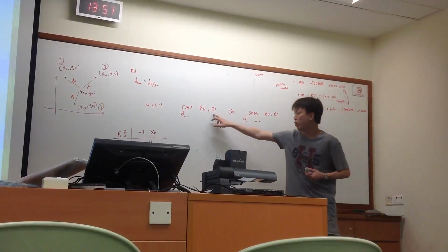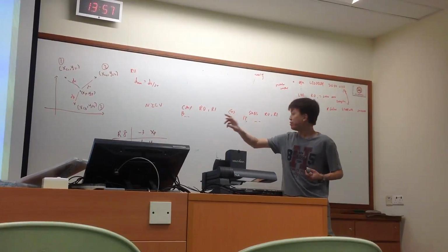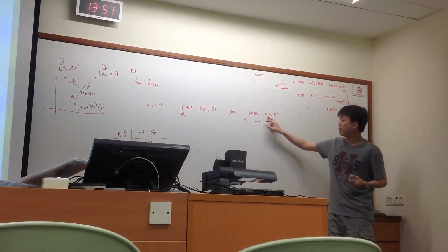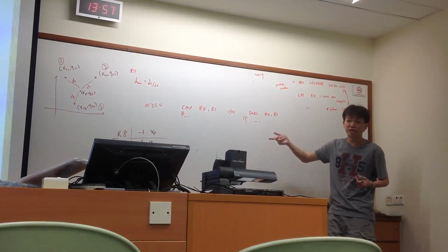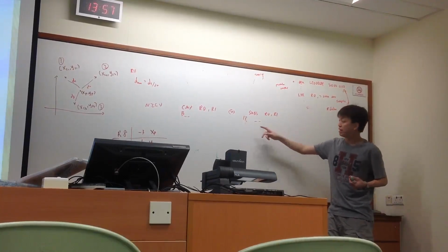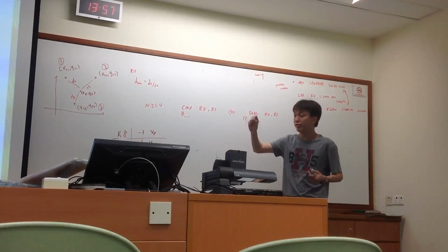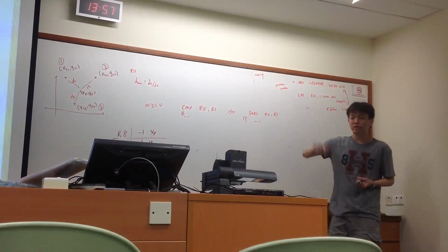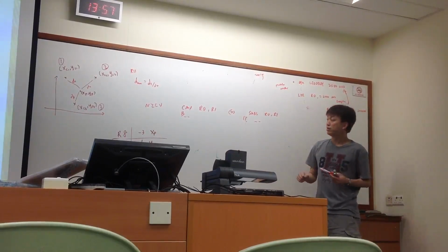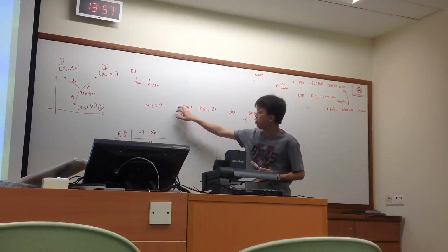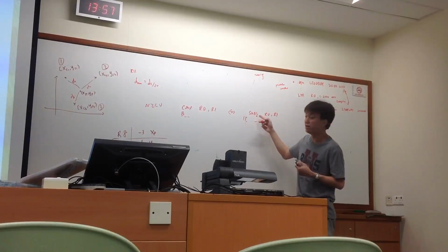The difference between compare and subtract: compare really just compares. For subtract, after they do the subtraction, they will update your R0. Your R0 value will be changed after this line. But for compare, the R0 minus R1 result will just simply be discarded. They just throw it away. They only try to update the NZCV flag.